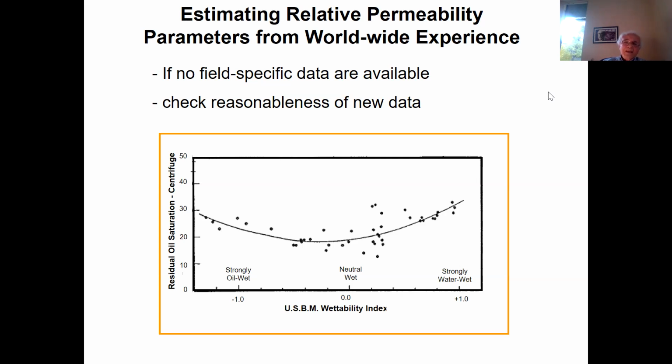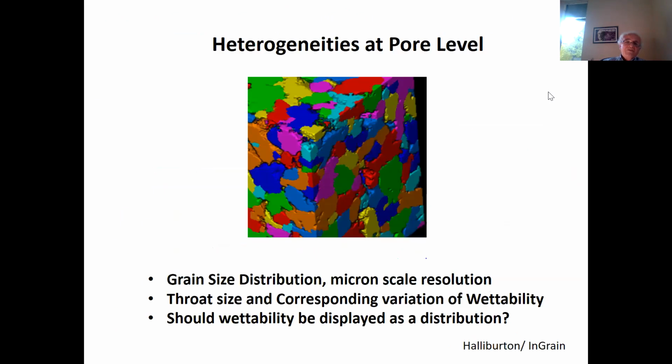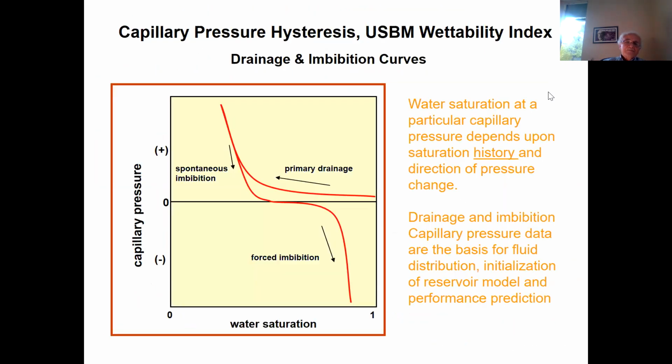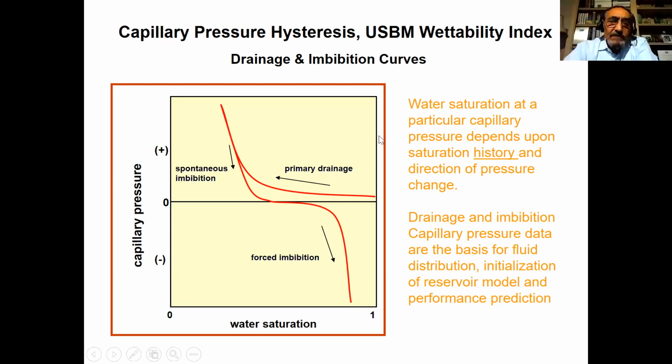Even if you go to your capillary pressure curve and the negative part, there we actually see that. Suppose I have a strong water wetting. That means there is going to be no contribution from the negative part of capillary pressure. But if you have an oil wetting, there's a lot of contribution from the negative part. That means in a large oil column, I prefer to have an oil wet system. So I think that's my comment.